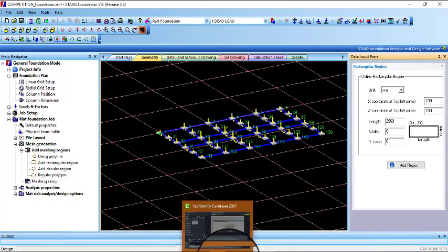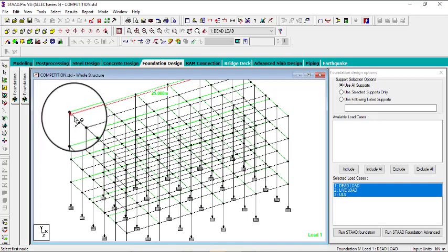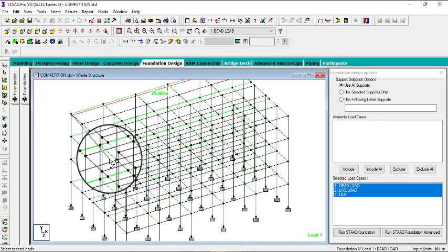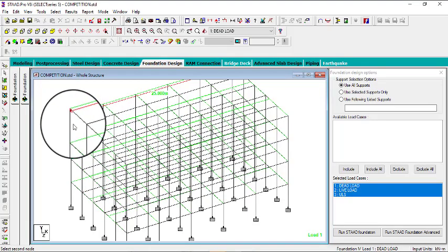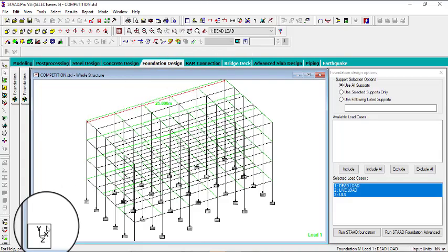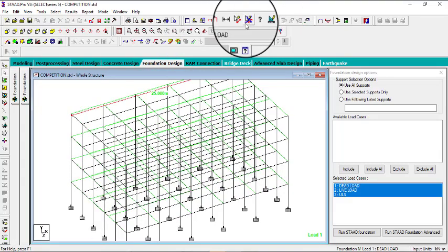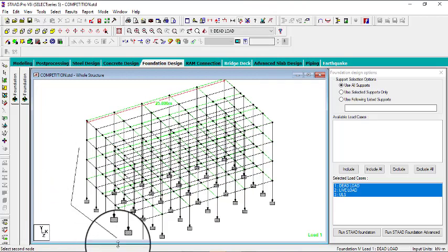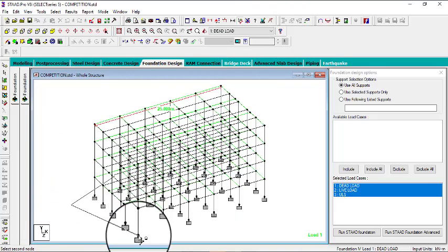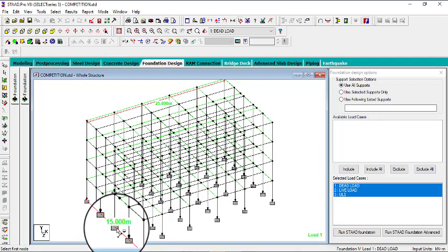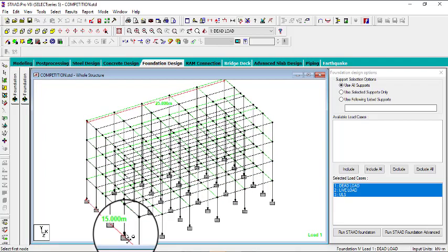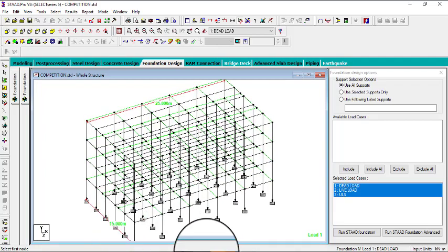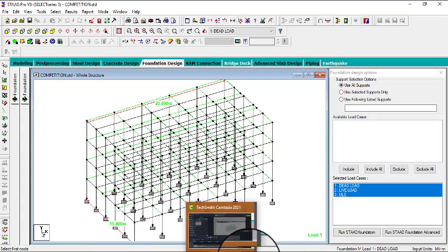Then what about the width? You can do the same thing for the width in Staad Pro. Confirm the width. From this point, we can measure it from the bottom to avoid confusion. So pick it and then measure from here up to here. Okay, so that is 15 meter. 15 meter plus 460 again will give us 15,460.